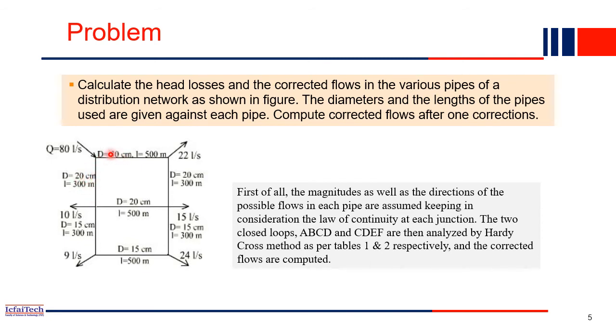So this is a wider pipe, which means the flow will also be high and more water will go in this pipe. So the initial guess may be 50 going here and 30 going here. Again, from this junction 30 is coming, and 10 is anyway going out, so the remaining 20 will be passed to here and here. Something like that we have to follow.